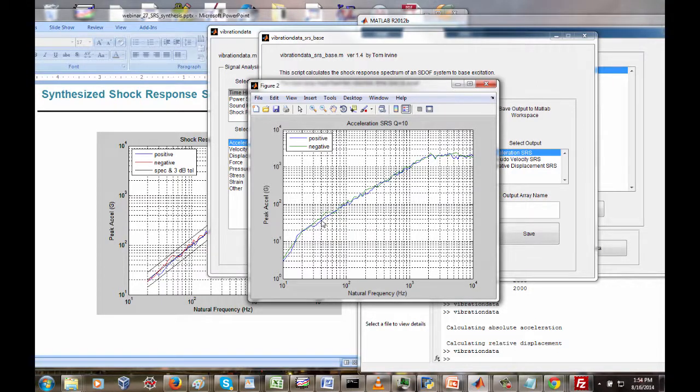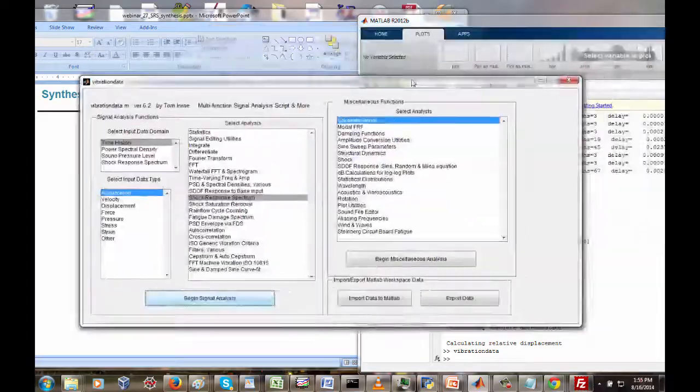But as long as the natural frequency of our component is, I'm using 40 hertz because that's 1 octave above 20 hertz. So as long as we have 40 hertz or higher, we're probably not worried about that response energy down there. But on the other hand, sometimes we might have an isolated component, and our component might be isolated to 20 to 30 hertz. And in that case, we'd have to be a little more careful, and we probably should extrapolate our spec down to 10 hertz, which would be, for this case, 10 hertz, 10 Gs. So that would have been a little bit better choice, but again, it just depends on what the natural frequency is.